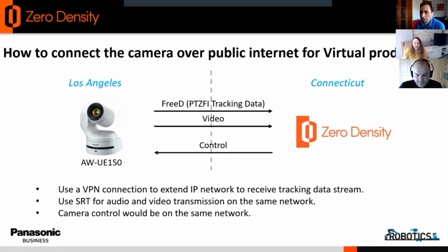When you create a movement, all the axes, pan, tilt, zoom, focus of the camera, plus horizontal and vertical of the dolly and totem, everything is synchronized. There is a timeline, you define the time. Normally you create some keyframes along the way, so start position, middle position, end position, for example 3 keyframes.